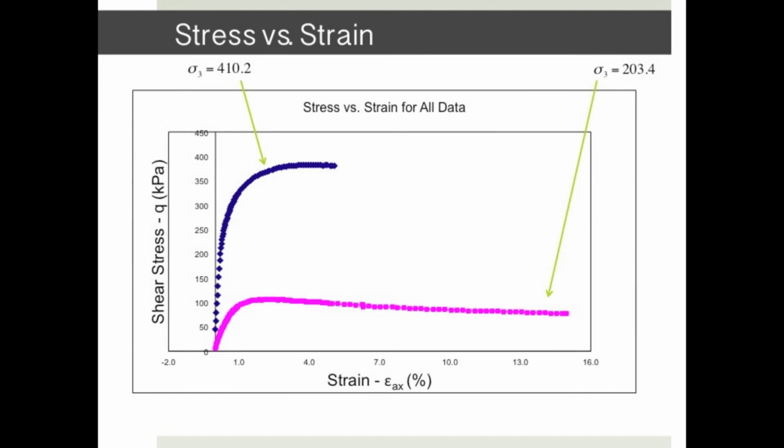Each of the two plots displays a linear portion, peak at failure, and residual straight line portion post-failure, which is similar to the results of the unconfined compression test. Other popular plots for the consolidated undrained triaxial data include average stresses versus strain, void ratio versus strain, and pore pressures versus strain.